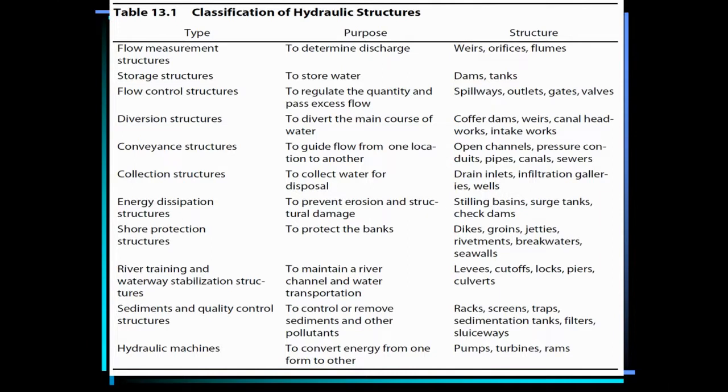We talked about surge tanks when we were discussing fluid mechanics in 233, when we were talking about water hammer. Water hammer, that sound, is due to the compression of water. We mentioned that water is compressible. Sometimes, due to certain hydraulic phenomena, water can be locally compressed, and it makes that sound as if